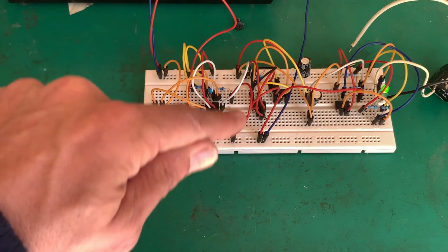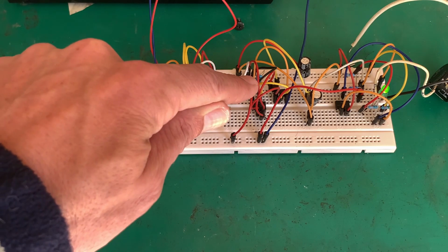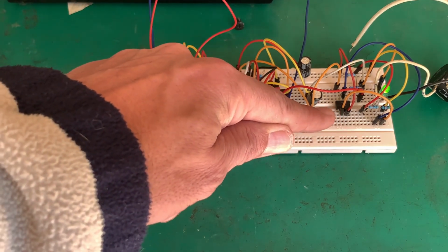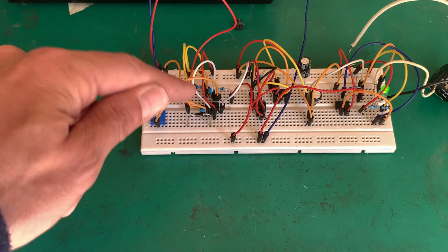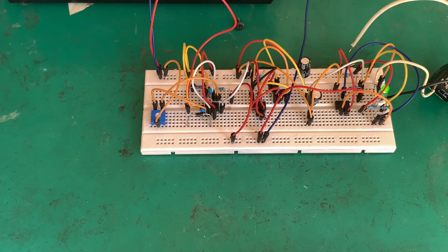But by creating the split rail, we've now created an offset. So what we could actually do is have powered this with this, and our battery voltage we could measure right down to 0. In theory, we can't with the circuit, because remember, we're using the battery to power the whole circuitry, and we're just regulating it as we're going along.